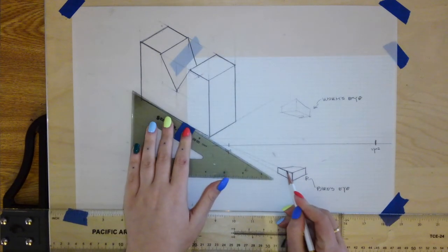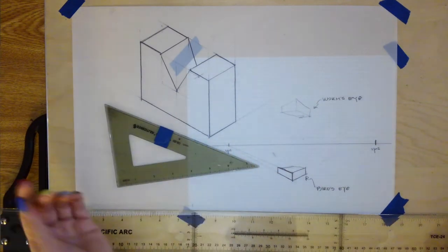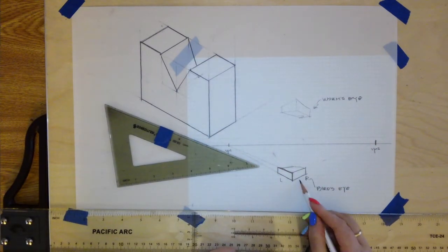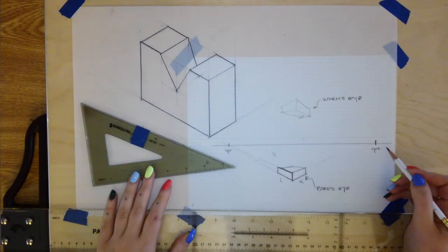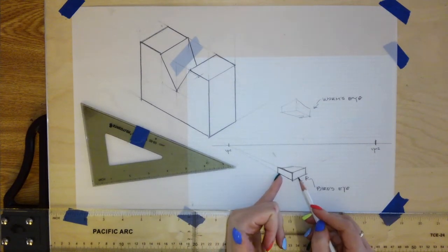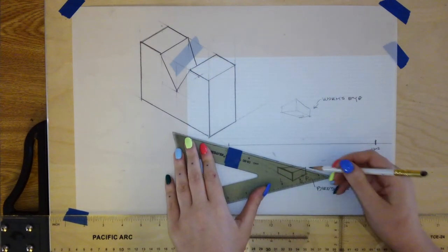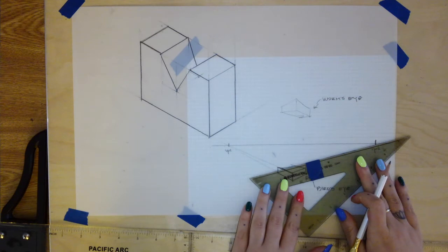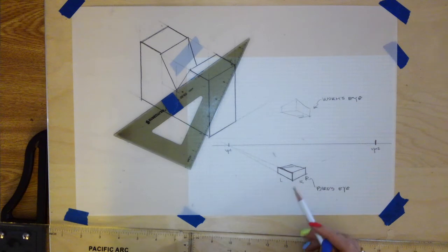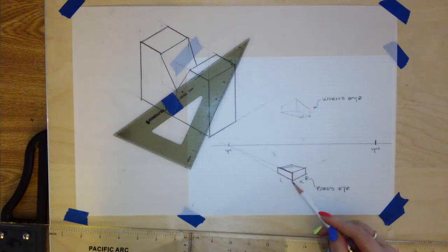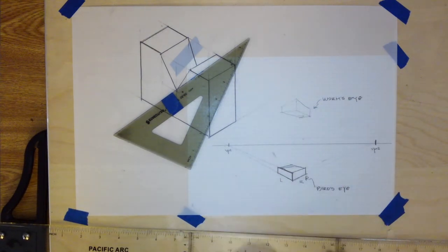Now, once you get the front two faces established, then you switch your vanishing points. So on this side, if we call these like the left and right, we were projecting the left side towards the left vanishing point, we were doing the right towards the right vanishing point. Well, once I get those two faces established, then I flip-flop. So then I would make the right go towards the left, and I would make the left go towards the right. And so then I have this drawn as 2-point perspective, where they're getting closer and closer together, or they're getting kind of smaller as it gets further away from me as the person viewing it.